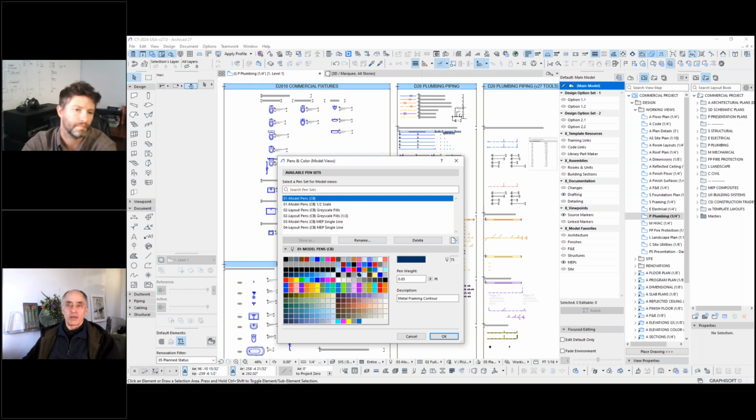And of course, if you made pen 6 a heavy line or something like that, then the doors would look bad unless you went into every door you placed and every favorite to modify it. So I assume you've gone through and made sure that at least the defaults that they use in the objects, which are only about half a dozen pens, map to a reasonable value. Yeah, most of them are in the first row, so 1 through 20. So I've left those for that reason.